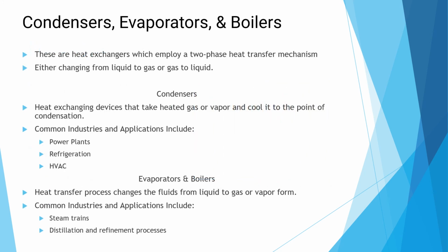Lastly, we have condensers, evaporators, and boilers. Boilers, condensers, and evaporators are heat exchangers which employ a two-phase heat transfer mechanism. In two-phase heat exchangers, one or more fluids undergo a phase change during the heat transfer process, either changing from a liquid to a gas or a gas to a liquid.